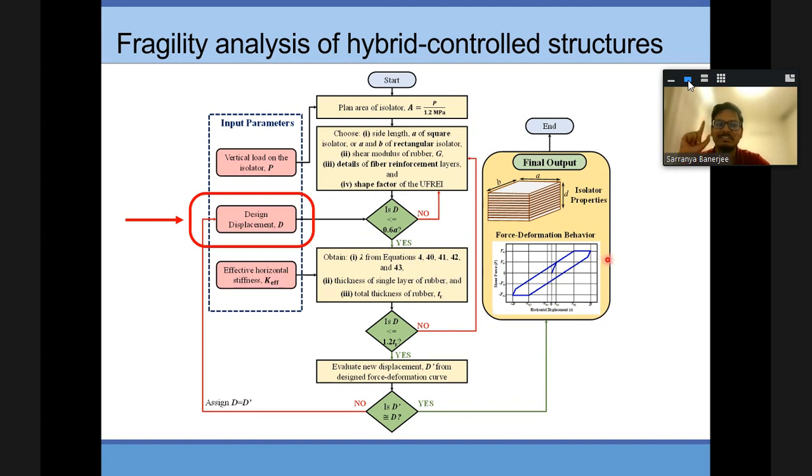And there is one more problem then. Now, if we include the equivalent linear model, we only have one stiffness. So our idea of using two TMDs, one with the stiffness for the stiffer case and the second one for the other, now we cannot use two TMDs. Now we have to use one TMD with only one stiffness. So that is one more problem.